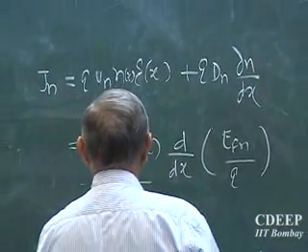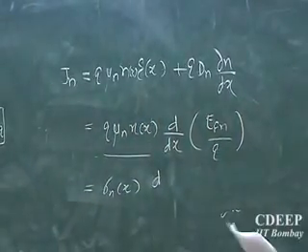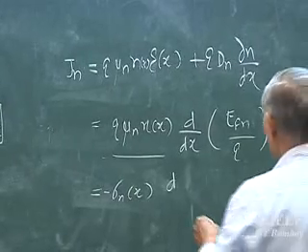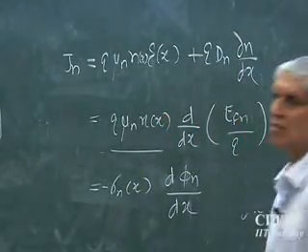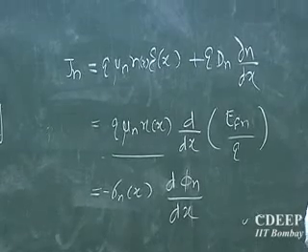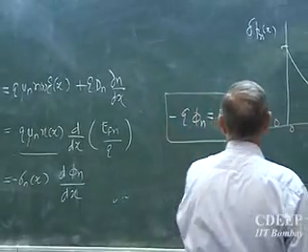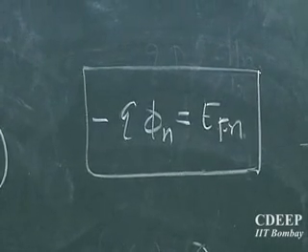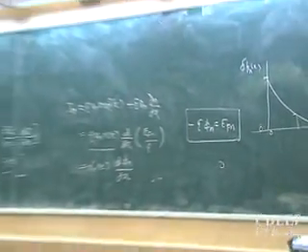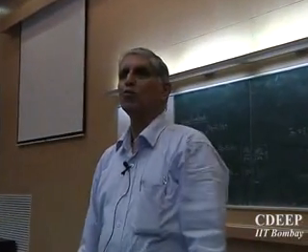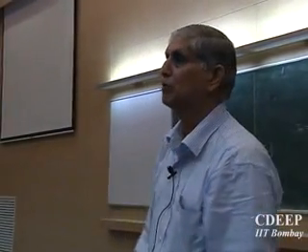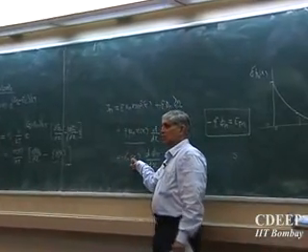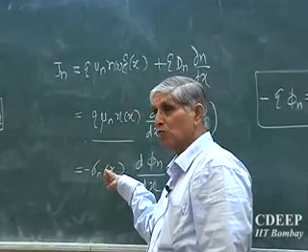So we say sigma nx times, and what is Ef by q? If I put a minus sign for n type, voltage. So it's called Fermi potential, where q phi n is EFn, where phi n is called Fermi potential. Is that word Fermi potential clear? E by q is voltage, energy by this is voltage, E is qV, electron minus charge. So q phi, instead of E by q I can write Fermi potential. So variation in Fermi potential is related to the net current and also the conductivity term, which is a function of x.